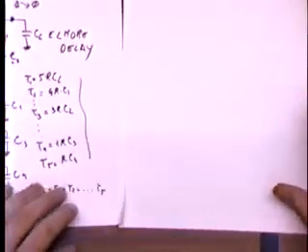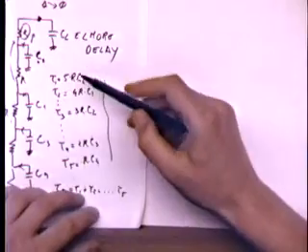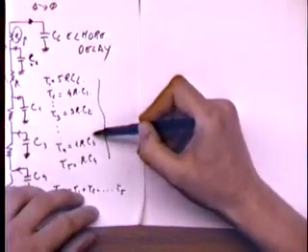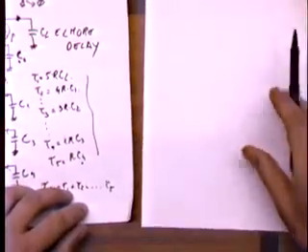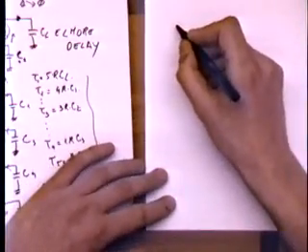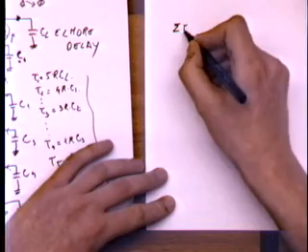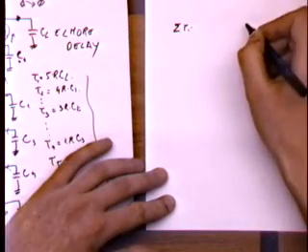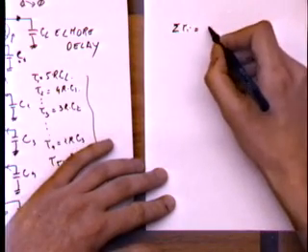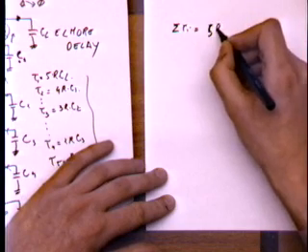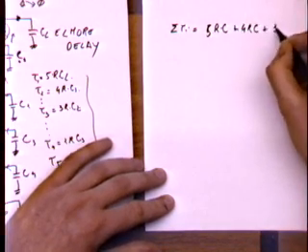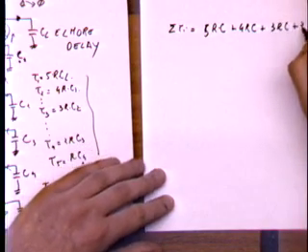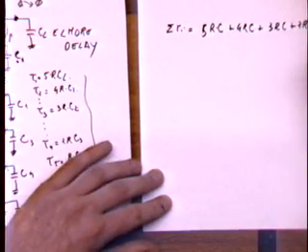So what's the implication, okay? In order to get the implication, let's assume that CL is equal to C1, is equal to C2, to C3, to C4. These capacitors are all equal. And let's try to compute the sum of tau i when all capacitors are equal. This is going to be equal to 5RC plus 4RC plus 3RC plus 2RC plus RC.